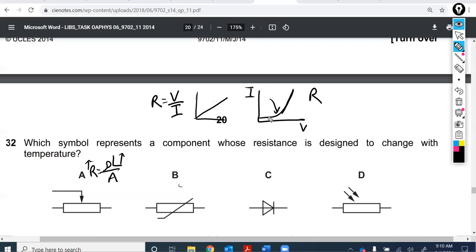If we have a flat line like this on an IV characteristic, remember that the resistance is V over I. So if we plot voltage against current like this, then the slope of this gives us the resistance. So when we did our resistance lab, we said, well, we'll plot the voltage on the y-axis against the current on the x-axis, and that way the slope is our resistance.